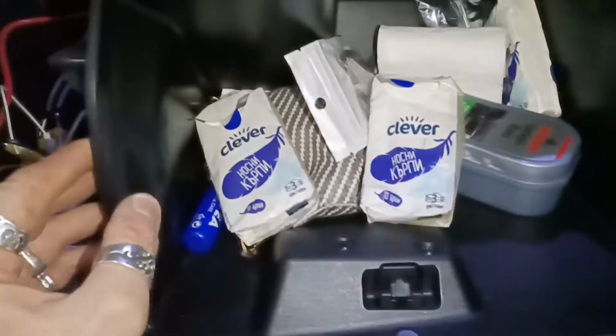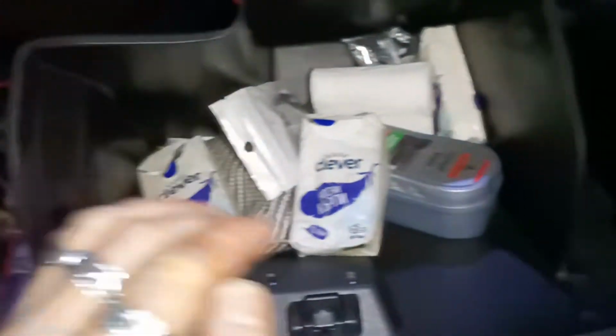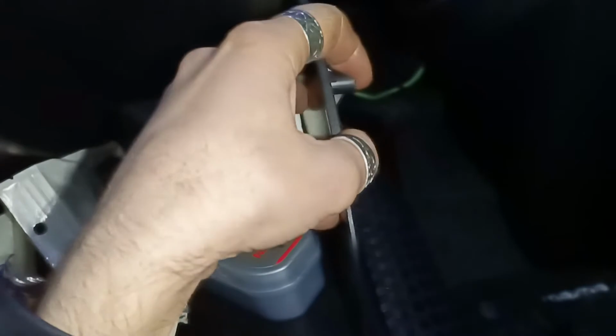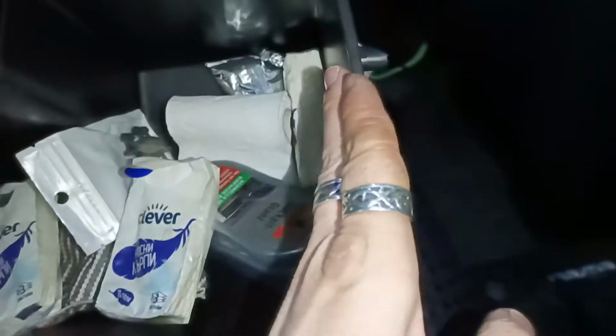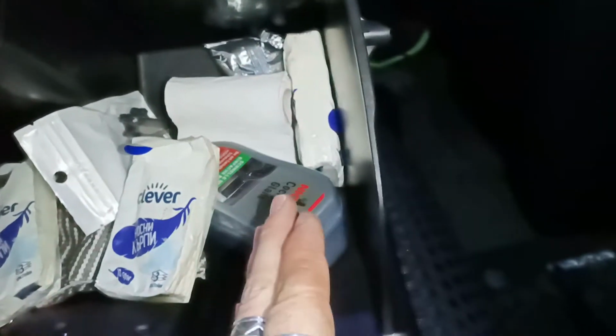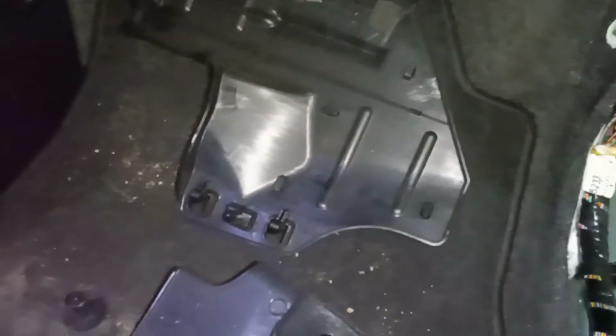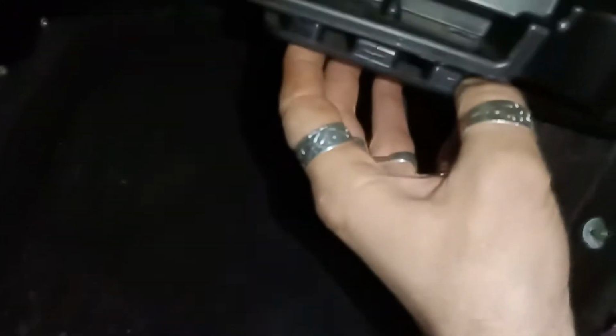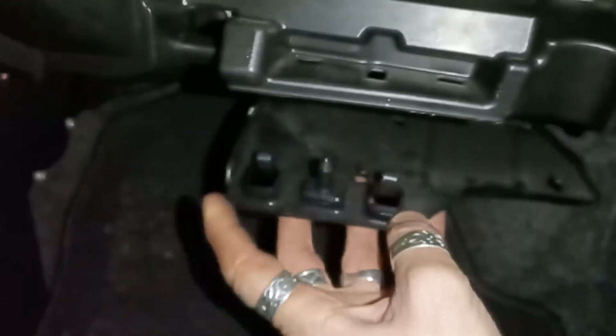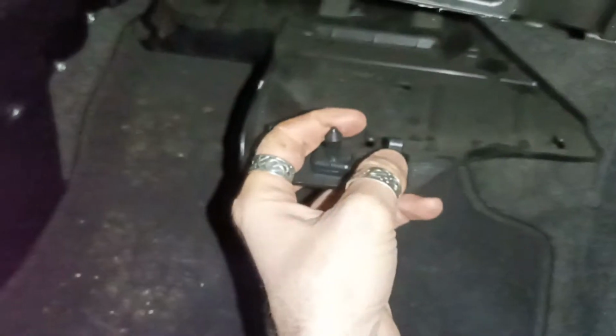To go to that position, you need to remove the glove box first. The glove box is easy to remove. Squeeze with one hand here and the other hand here while opened, and these pins will go inside when you squeeze and allow the whole thing to fall, and you just get it out. Then that's the floor. This is being held like that here, so you squeeze those here and it falls off. You need to remove it.